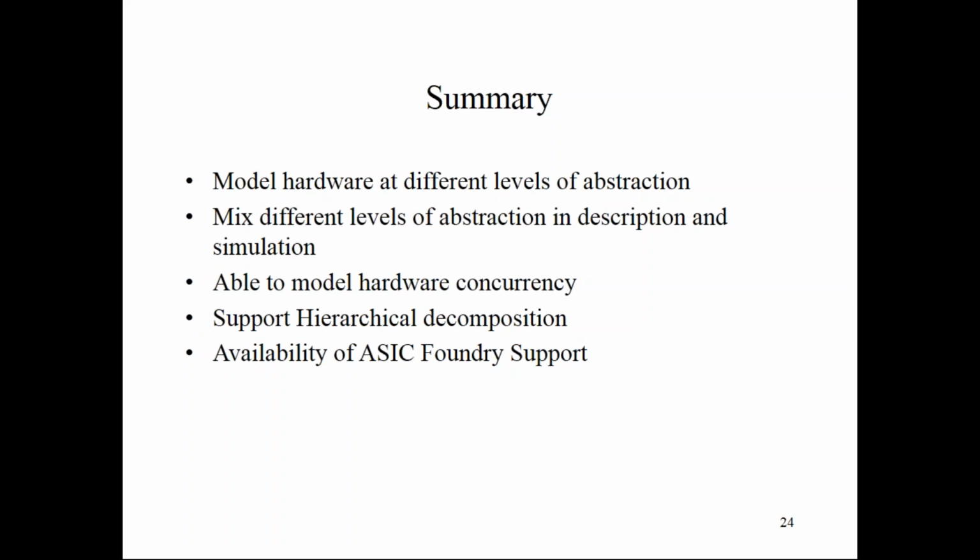We describe hardware concurrency through the structural modeling. The initial statement is used inside the test bench to describe the input functionality in terms of hardware concurrency, and the initial statement is used only in the simulation, not inside the actual design.